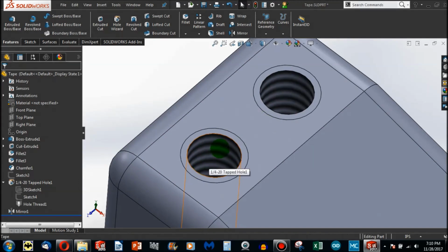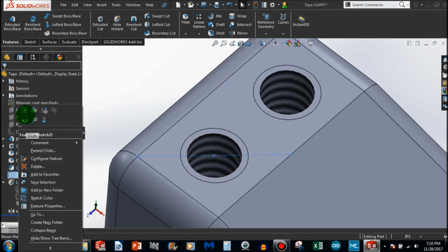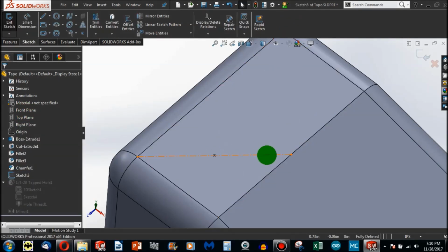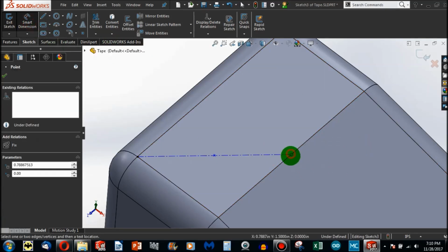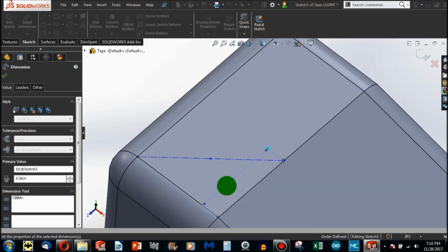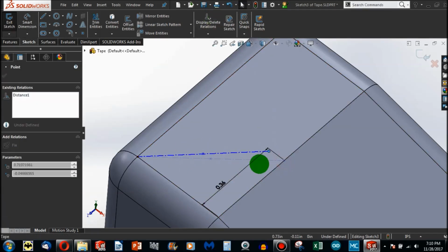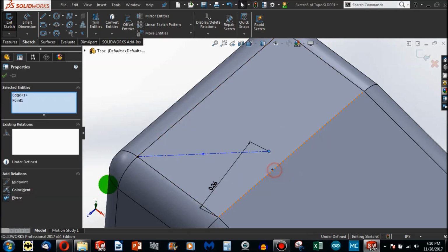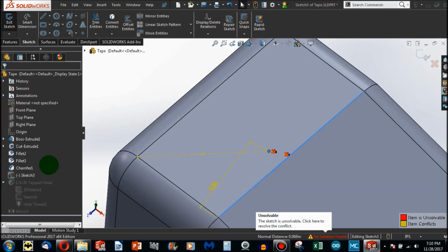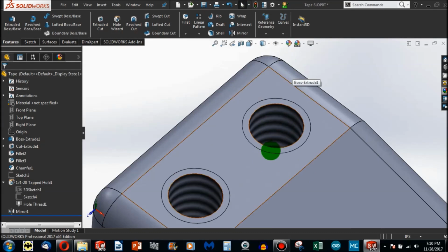The mirror image can be very advantageous because if I wish to go edit the sketch, if I would have made 2 holes, I would have been having to adjust the position of 2 different holes. By being able to adjust only one, the mirror automatically updates. And so I don't have to worry about the positions of other holes.